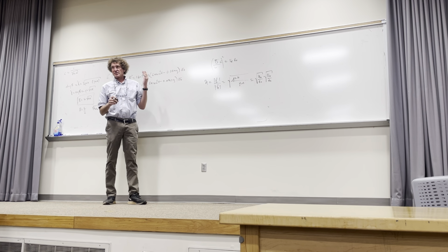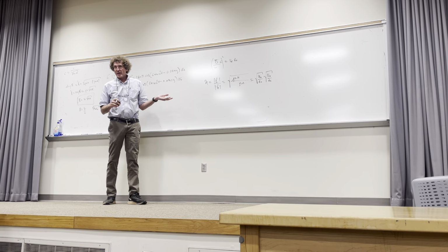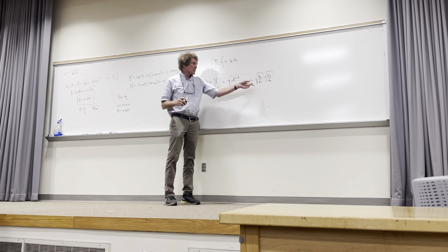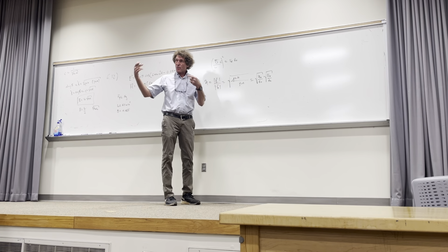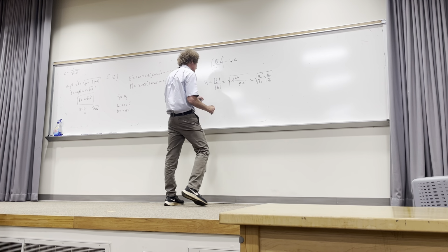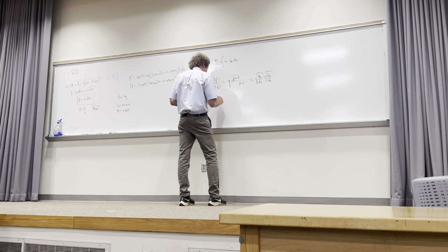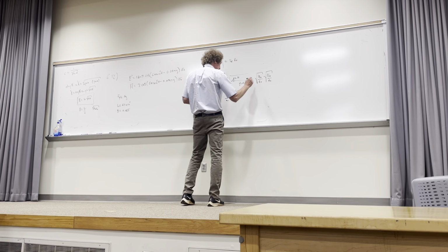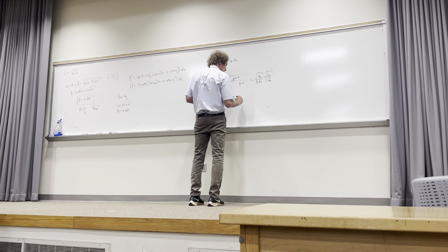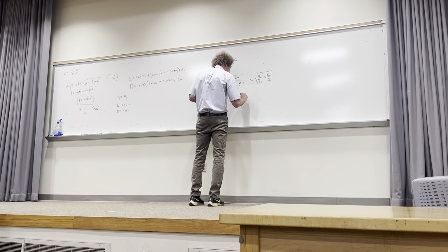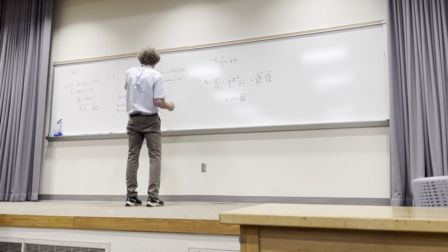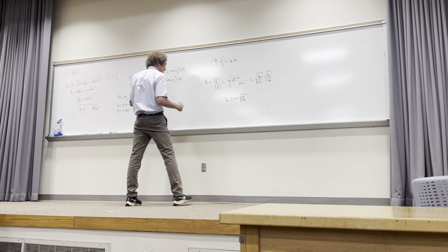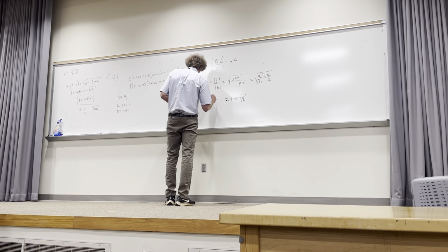I want to make sure you see the logic. Now, what is the square root of mu naught over epsilon naught? It's called the intrinsic impedance of free space, or eta naught, or 120 pi. So now I can say the ratio of E to H is equal to 120 pi times the square root of mu relative over epsilon relative. Well, E is 120 pi, and H is 2, so the ratio of that is 60 pi, isn't it?